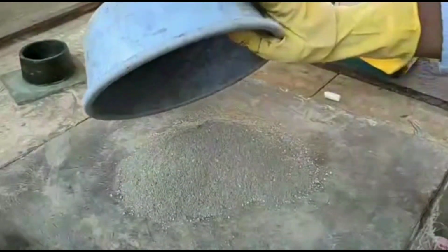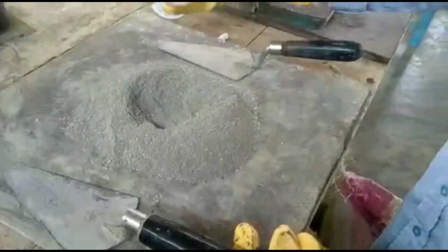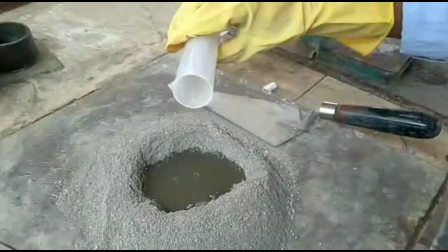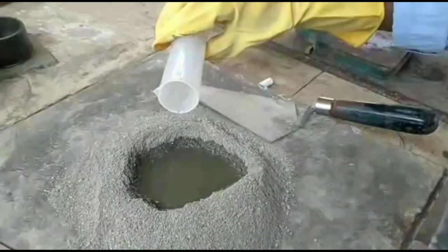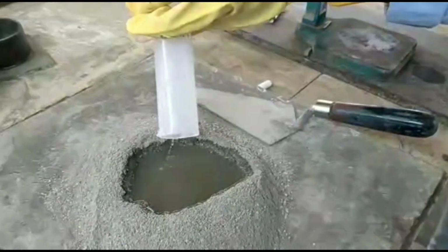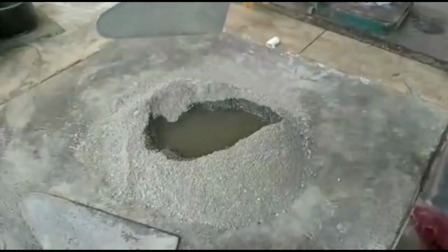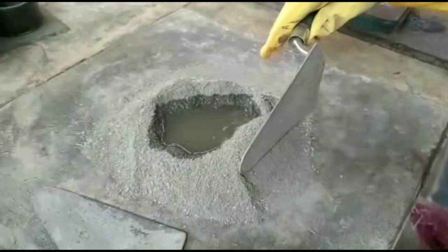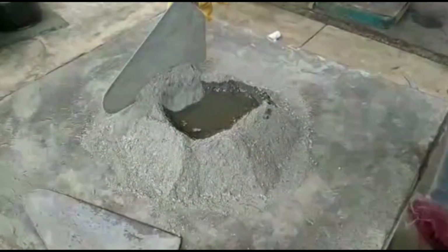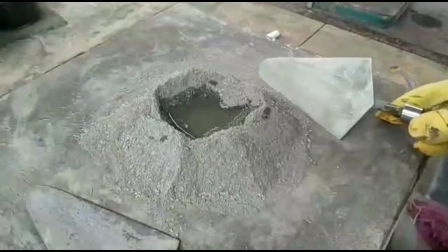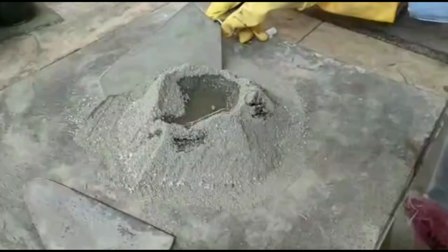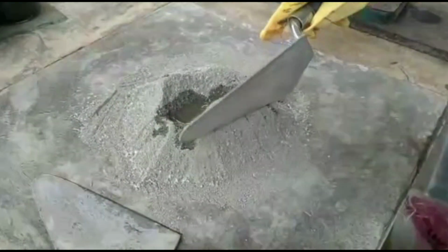Now we have to pour the cement and sand onto a horizontal plate. Now we have to pour the water, 84 grams, considering the 33% normal consistency we have determined for the cement. Slowly we need to add the water, about 84 grams. With the help of a trowel we have to mix slowly. You can see here slowly we are mixing the cement and the fine aggregate of sand with the help of the trowel, to make a homogeneous mixture.